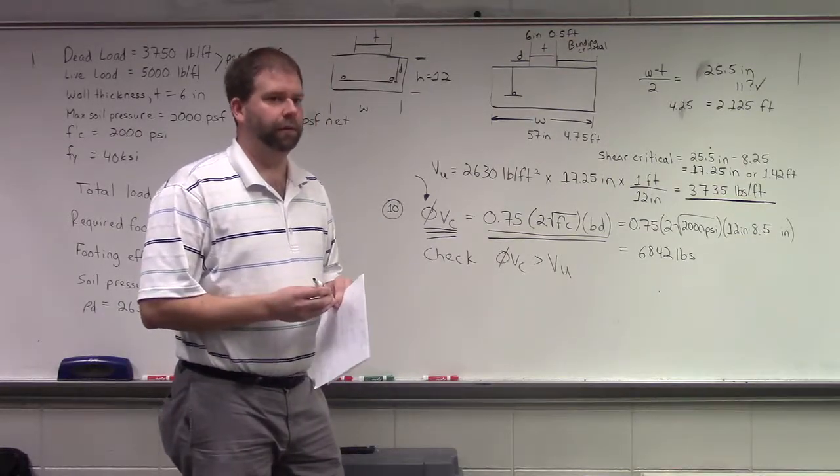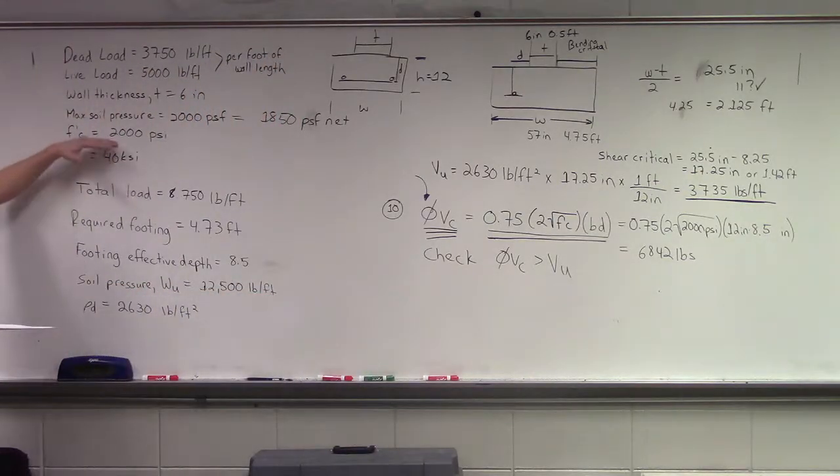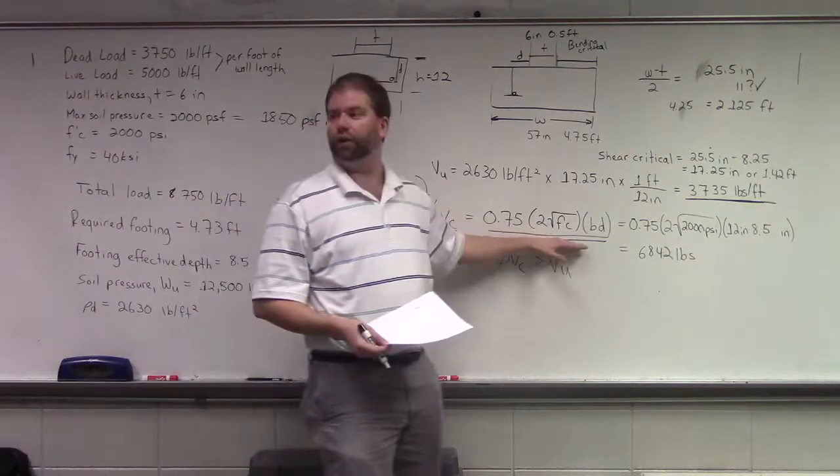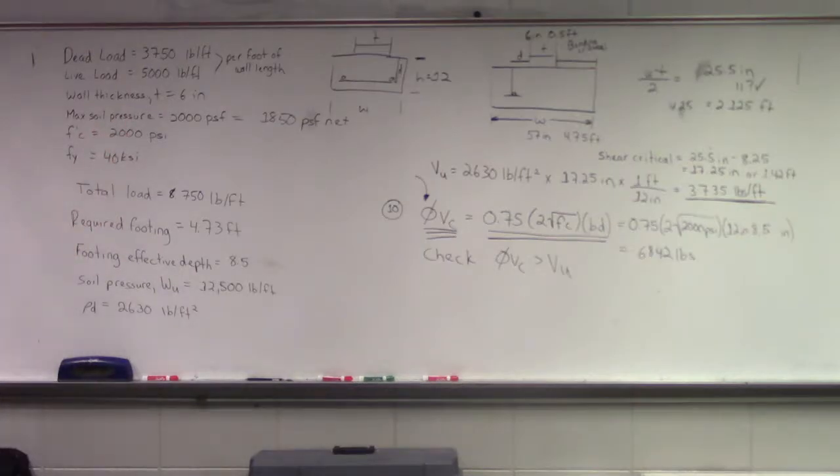I'm imagining in our problems we're going to go through all this, so find the minimum, or what would something else that would be available to you be? The strength, or the design of the concrete. Well, stronger concrete, right? Because we'd want to increase this value. So then you could look at 3,000, 4,000 PSI.